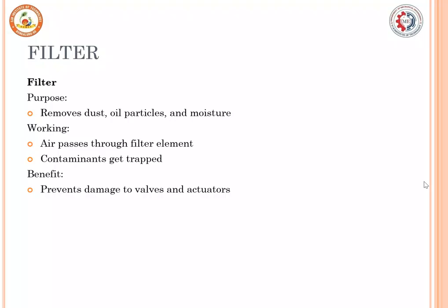Next we are going to use the filter. By using a filter, it removes dust, oil particles and moisture. Working: air passes through the filter element and contaminants get trapped. The benefit is that it prevents damage to valves and actuators.